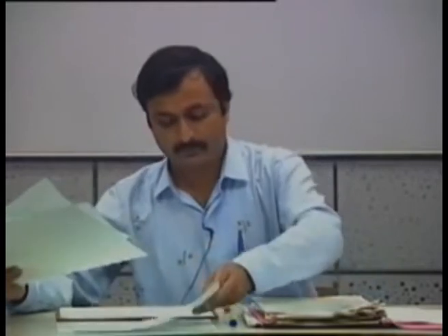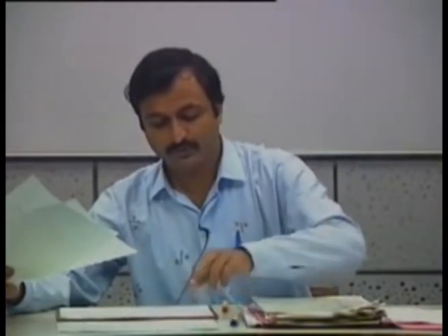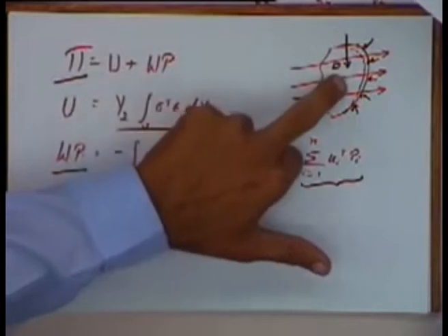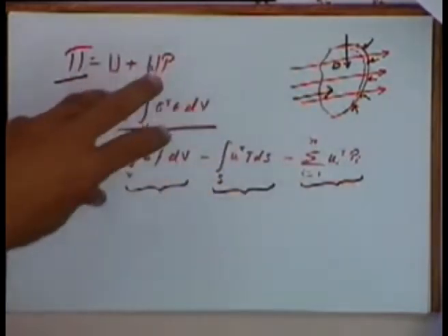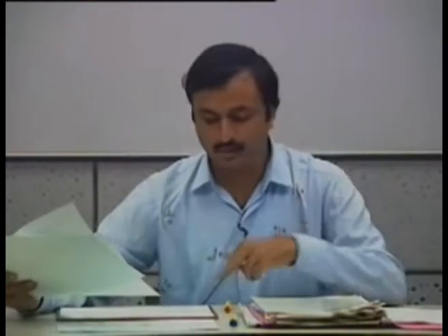So aren't we taking strain energy into account in the work potential equation? Because work is done against deformation, I mean work done for it to get deformed. That is the first term of the work. No, work potential is the work done against the external forces. Strain energy is whatever energy is retained inside because of the strains in the body. The two are because of two different terms. The sum of the two will be the total potential energy.